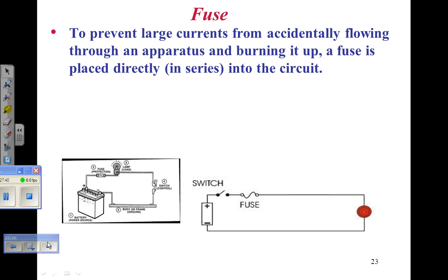In electrical energy, AC energy, it's created 60 cycles a second here in the United States. Okay? So 1/60th of a second is one wave. And 1/4 of that is 1/240th of a second. Is that correct? And that's how long it will take to kick off at 200%. That's known as inverse time. The higher the overload, the quicker it'll kick off.